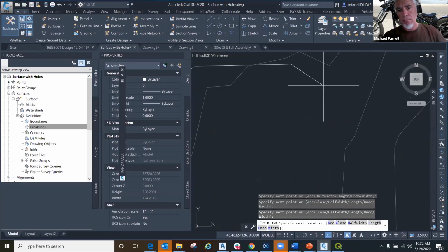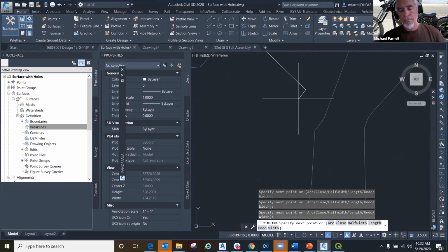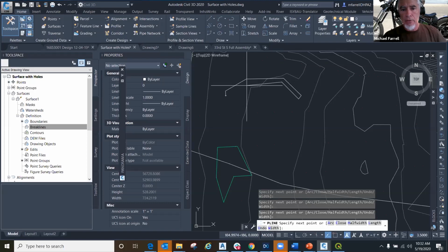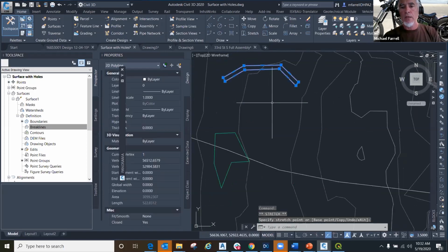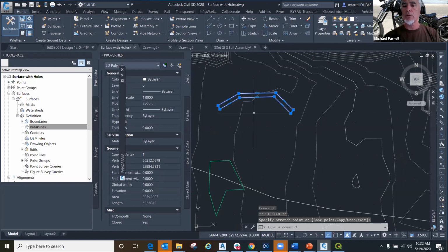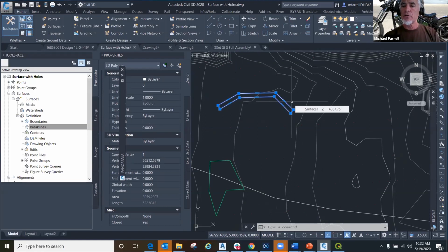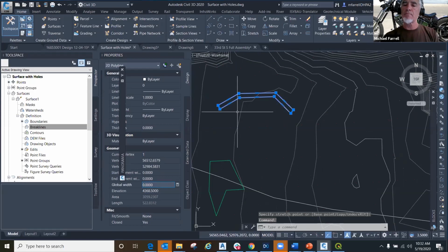Let's say this is some head wall structure. And it's just terrible CAD, so don't give me a review. Okay. Just winging that in there for you. So let's say you had a head wall structure like that. And I'm going to go ahead and set his elevation using the tooltip there at 4368.5. Okay. So that's the top of head wall. That's what the surveyor gave me.